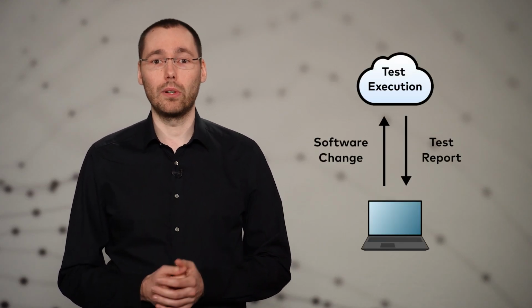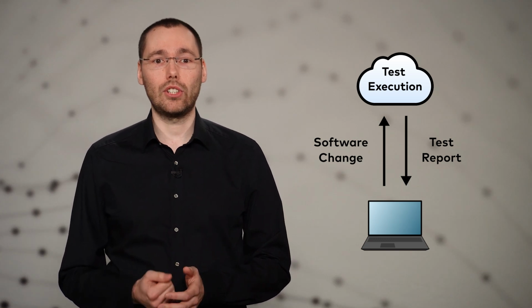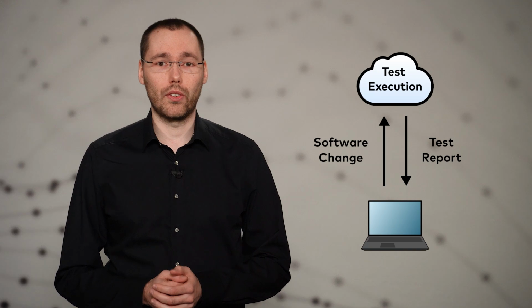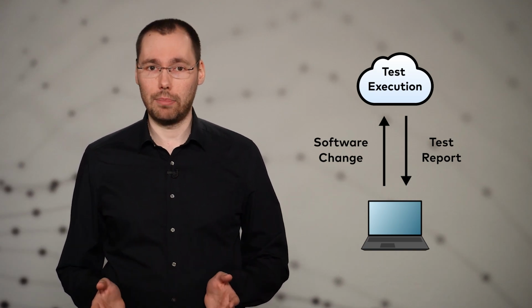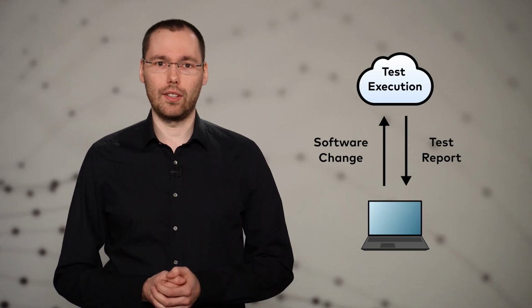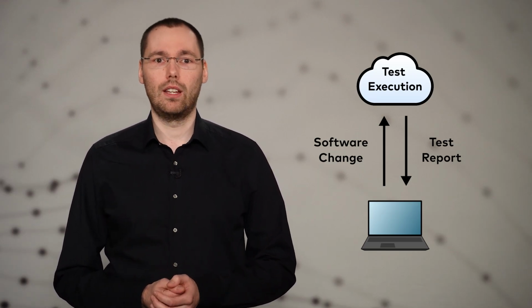With such a virtual environment at hand, we could go even further and integrate HIL into our CI/CD pipeline, where tests are executed whenever a change has been made to the software. With sophisticated tools, the test framework can be easily expanded. For example, if we later realize that a temperature sensor is required, we can simply simulate it within our test tool. These simulations can not only be used for hardware testing, as I have hinted at several times already.